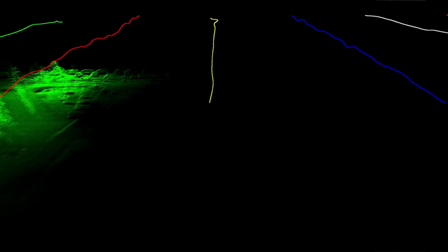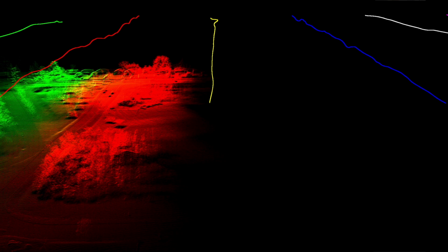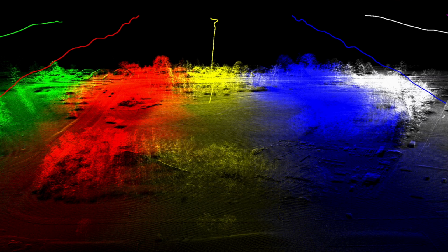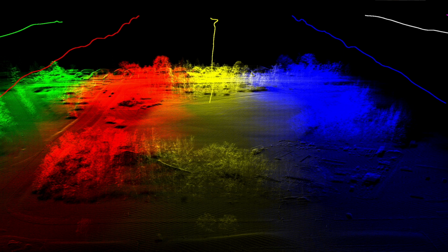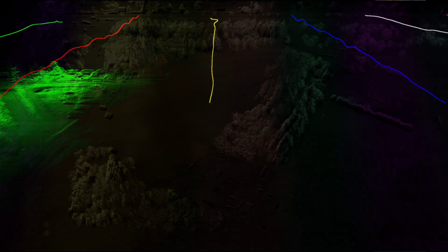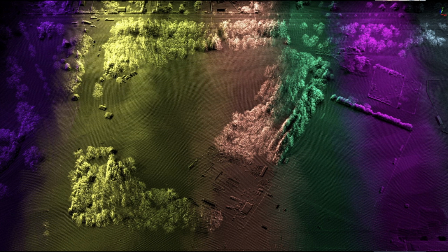So this is what we get when we cut those out. This is a very important step in the post-processing of LiDAR data. So we have our trajectory, we've painted the points in, and then now we need to clean it up a little bit. And you can see what it looks like when they are all together. So there's no fitting that needs to happen. These should just fit exactly where they belong because the trajectory was accurate. And everything starts from there.